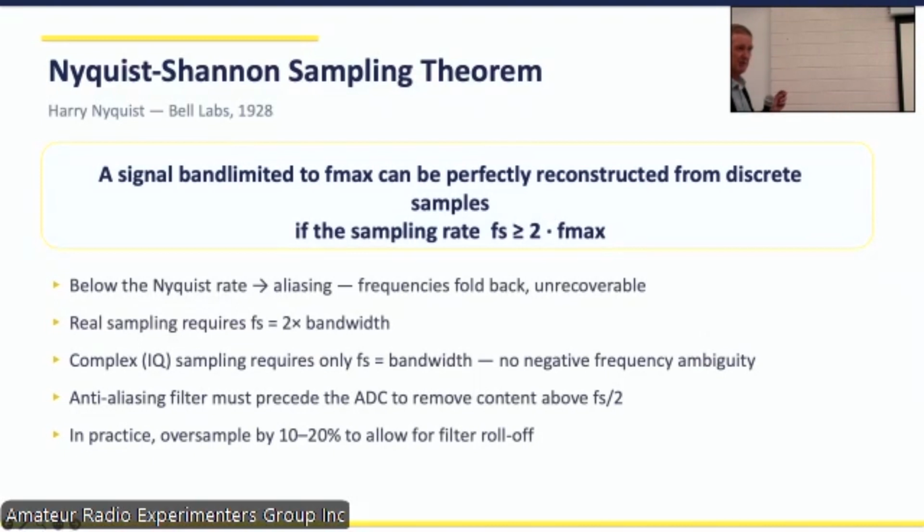And that's the big thing to remember. Anytime you go down IQ, it is breaking the signal into two components which are mathematically easier to work with. It may look complicated, but it is significantly easier to work in IQ with most modulations and techniques than it is in real.